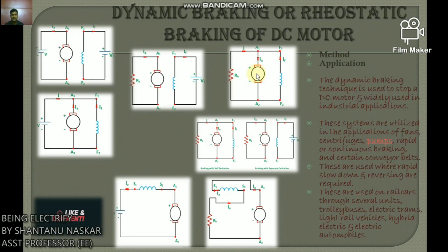During electric braking, the kinetic energy stored in the rotating parts of the machine and the connected load is converted into electric energy. When the motor is working as a generator, the energy is dissipated as heat in the braking resistance RB and the armature circuit resistance RA.